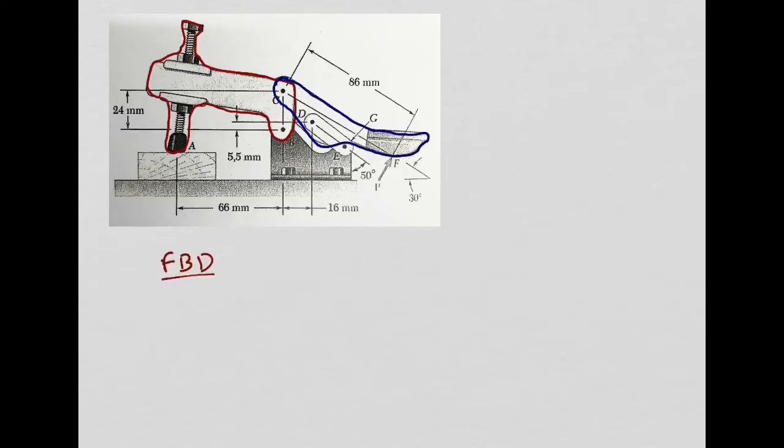So it is connected to this link CF at this hinge at point C. And then you have another link or another part, which is this one, DE. I'm underlining now in black. Or you can have the whole thing. You can have another free body diagram that can be all thing connected, right? So we have here many options to build our free body diagram.